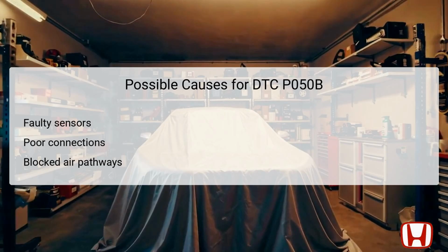Moreover, physical blockages in the air intake system, including dirt or debris in the air ducts or filters, can impede airflow, thereby affecting engine performance during cold starts. Identifying these issues requires careful visual and functional inspections of the intake air duct and housing. Additionally, any faults found in these components can lead to improper ignition timing, resulting in significant engine performance problems.